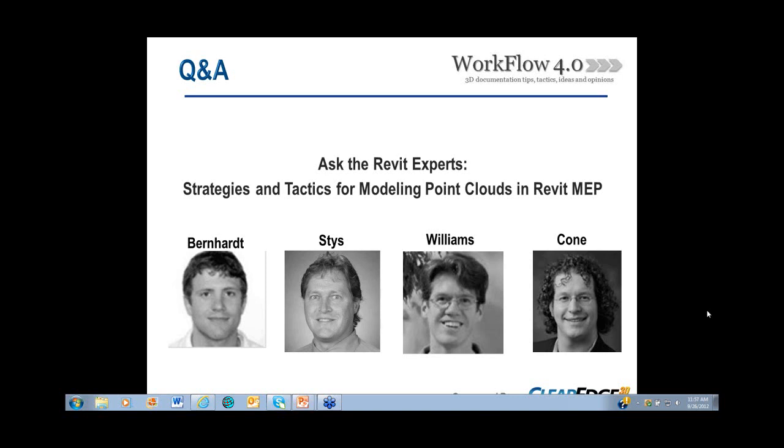It's a number of factors in terms of dependencies between elements and densities of elements in a view that will contribute to what most customers perceive as general performance. But as a general rule, once you get up to about 250 megs in terms of project size on the architectural side, it begins to hit towards the top end. But again, it's really tough to say in terms of a specific metric. Ultimately, there are limits to the overall scalability, and it's usually on very large projects.